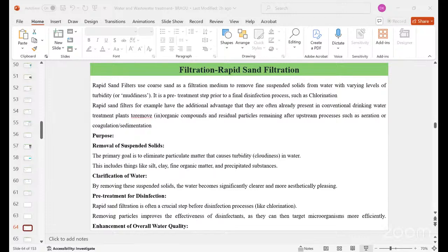Backwashing hydraulics. Backwashing is what removes the clogging effect in the filter bed, and it majorly involves reversing the flow of water to clean the filter bed. The backwash rate must be sufficient to fluidize the filter bed and also to remove the accumulated particles. The key hydraulic considerations during backwashing include the backwash flow rate, the bed expansion, and the water wash troughs design.